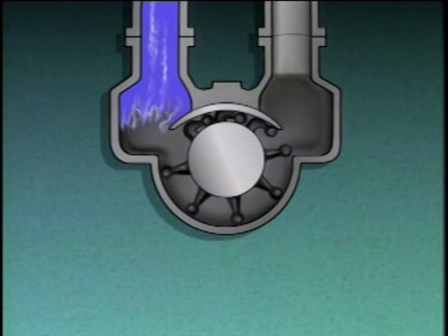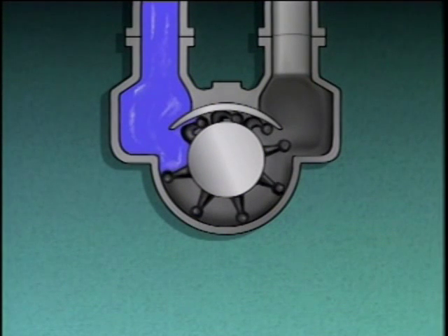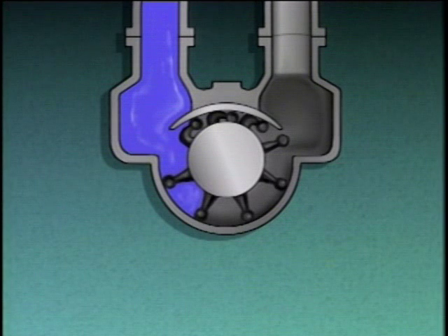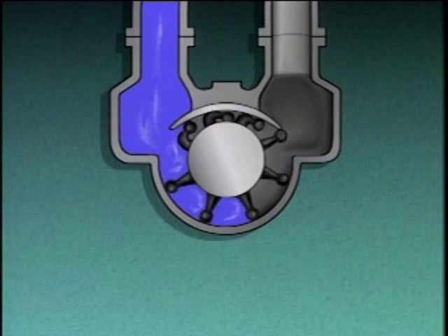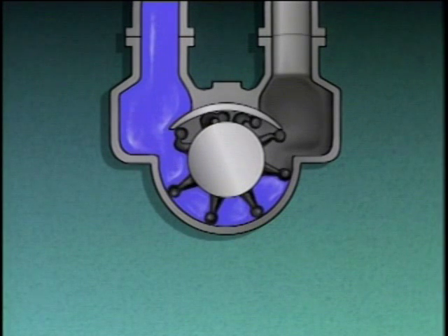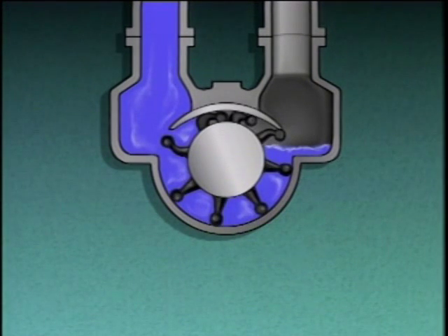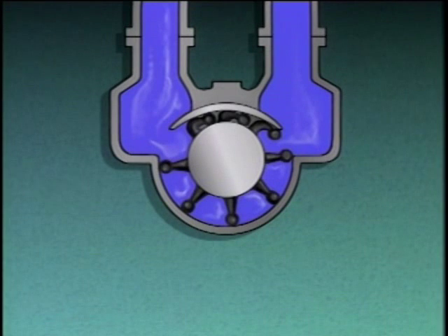When the pump operates, process liquid is drawn in from the suction of the pump and trapped between the moving vanes and the casing. The liquid-filled spaces are moved along until they reach the discharge of the pump. At the discharge, the rotor is closer to the casing, so the pumping area is narrower. As a result, the vanes flex by bending over into the spaces containing the process liquid. This makes the spaces smaller and forces the liquid out of the pump.